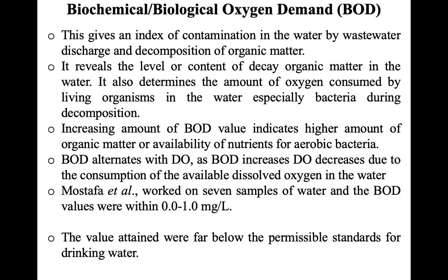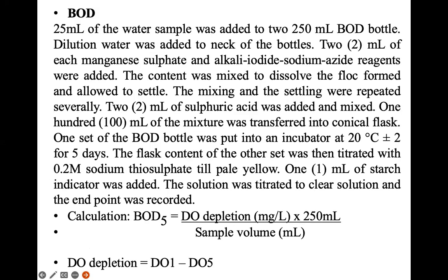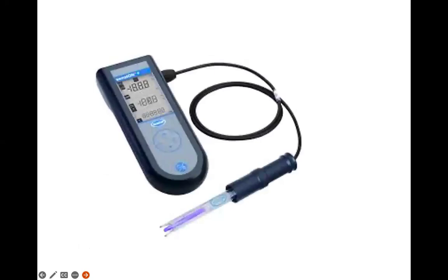And these days, we also have the BOD probe that can be used to measure the BOD for the first day. Then you keep your samples in an incubator maintained at 20 degrees Celsius. Use the same probe to determine the BOD after 5 days. Then you find the difference. That gives you an indication of the biological demand. That gives you the level of pollution of your water body.